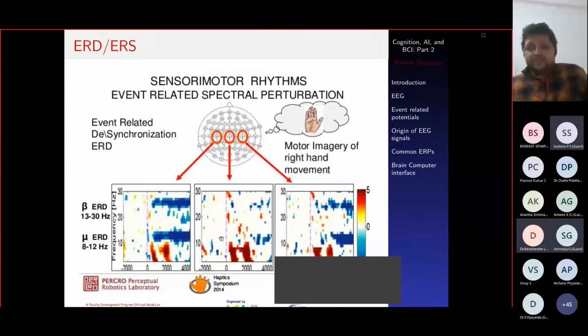Some you can use very liquidy, but you need to use a small amount. If you use something like ECG gel, you have to put a bit more. That's for the impedance of the electrodes to go down to a certain level. For a proper, less noisy EEG signal, you need an impedance of about 5 kilo ohms or lower. Otherwise, you will not get a good signal. It will be full of noise.